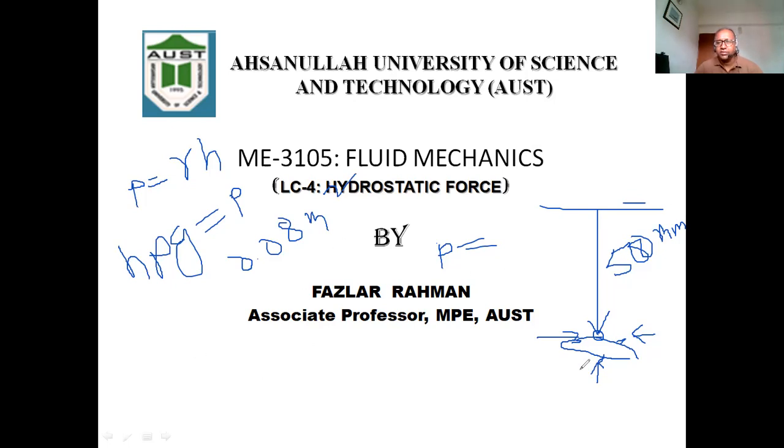Or if I call it a submarine at that depth, and just think the top surface is a roof, kind of horizontal or flat. If I give you the area, you can figure out the force, right? You figure out the pressure from the depth, then force equals pressure times area.